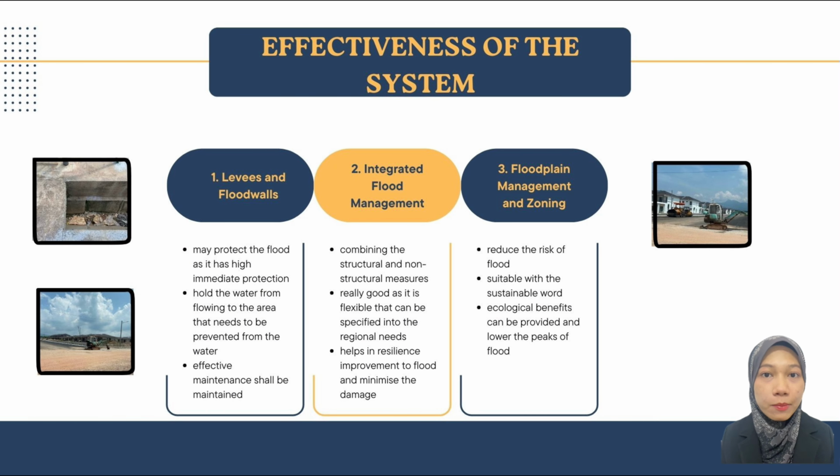In our first case study, the project team encountered several significant issues with drainage system implementation. Firstly, poor alignment was a major problem. Precise alignment is crucial to ensure that each precast concrete piece connects seamlessly. Misalignment can create gaps or uneven surface, hindering water flow and leading to blockage or leaks, which compromise the drainage system functionality.